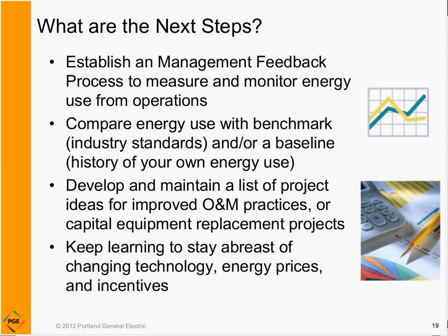So what are the next steps? I often get asked this question, and I always say the first thing is to get some kind of feedback process. Monitor what you're doing. Measure what's going on with pieces of equipment, and let people know about that. So when I say feedback, feed it back to the people who are using the energy. That's where I'd start. Compare that to other buildings or other industry standards. And we have many of those. We've got a staff here that can give you the standards for restaurants, for office buildings.